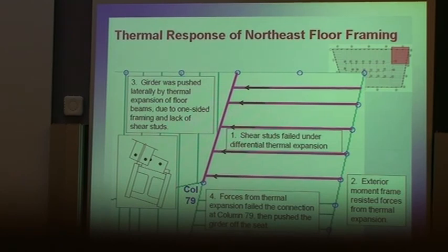In our models, we observed that this failure first happened at floor 13. Floor 13 collapsed in this region. The floor underneath was already heated. Fires were in the same location. They were weakened. They got this additional load from the floor above dropping on them, and they were already under pressure. So that triggered cascading floor failures in this region, and column 79 became unsupported, and that resulted in the column being buckled and unstable.